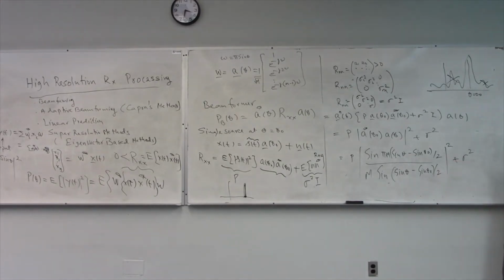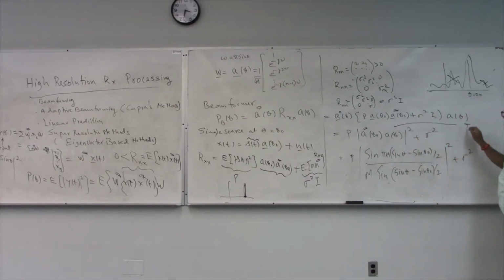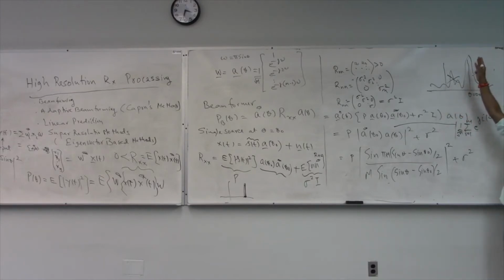I think I did this right. Any questions? You know how this is done, right? We went through this. This is the summation of e to the power j i (omega minus omega naught). Omega is pi sine theta. I just substituted it. And we went through this, right? i equal to 1 through M minus 1, squared, right? Last time. That's this expression. Or 1 over square root of M, absolute value squared, right? So you can see the beamformer also peaks at the right place.